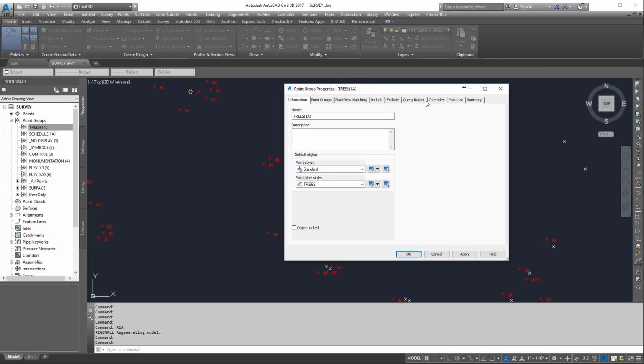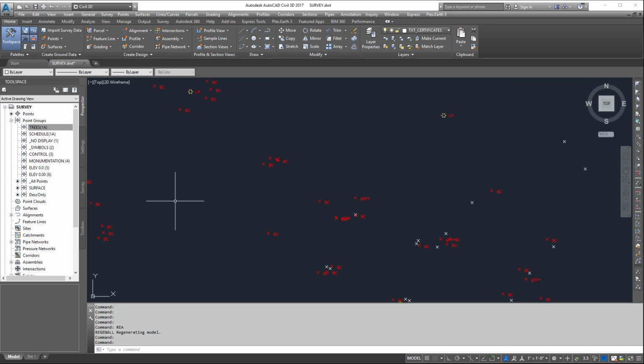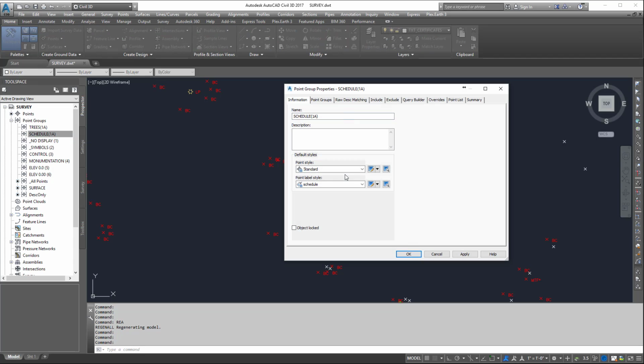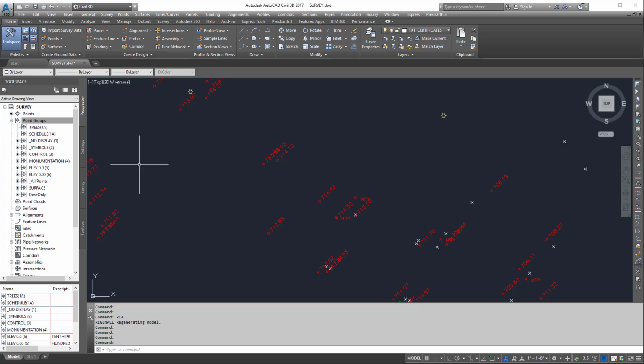So now when I go back to point list, if you notice, there's no points. So again, checking your point list, going through here, going through the groups, making sure it's all good. What I ended up doing is I just clicked on the entire thing of point groups and hit update all of them. And if you notice, that technically fixed my problem.